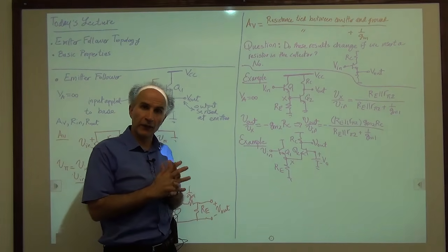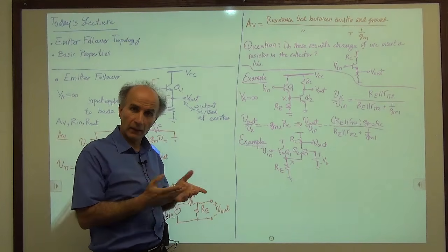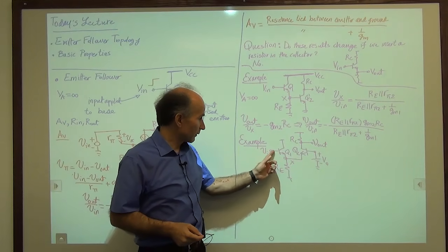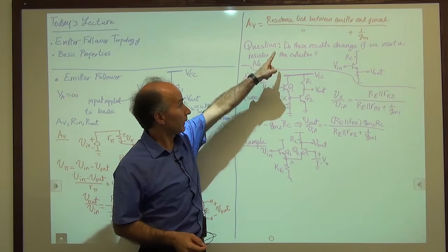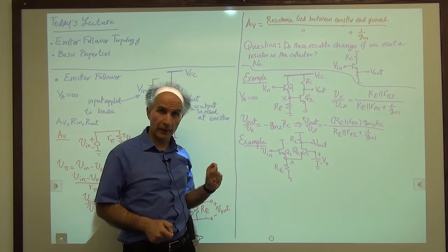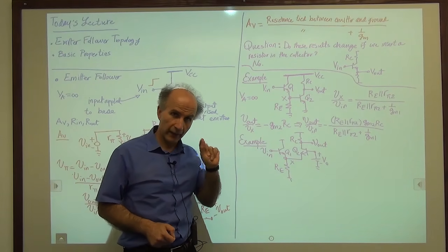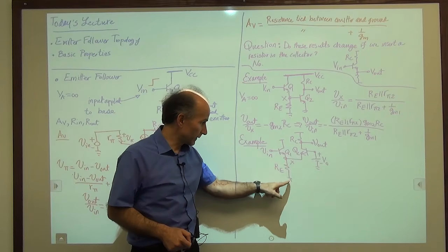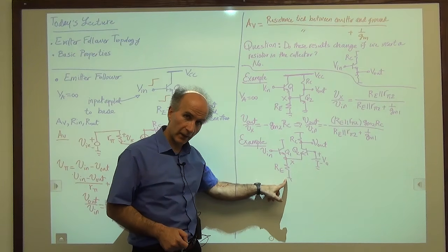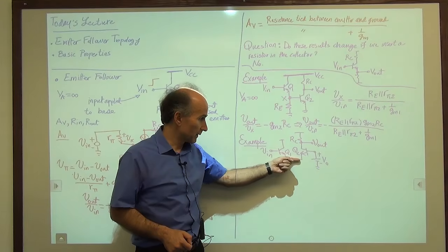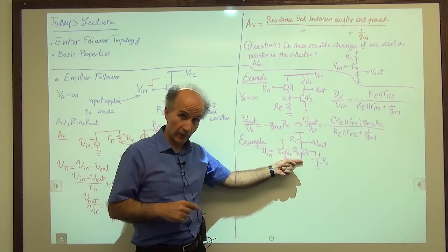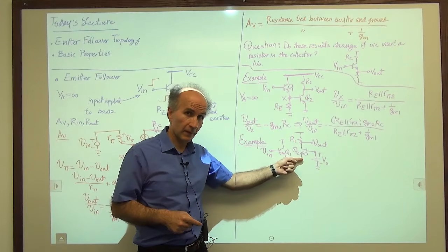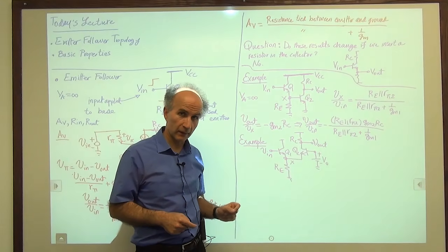Okay, so what did you get? Well, for Vx over Vin, we have the voltage gain of an emitter follower. We go back to that equation and try to find the total resistance tied between the emitter and AC ground. We have Re here, but how about here? Is there any current flowing through that wire when the signal is applied? If there is, then there's an impedance seen this way to ground as well.